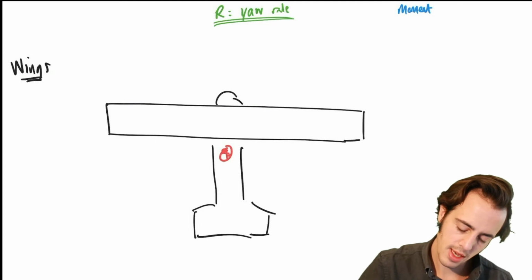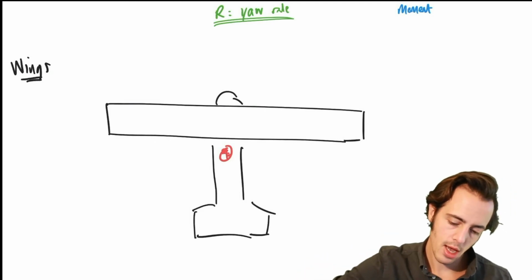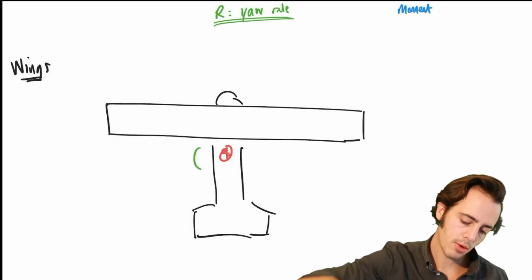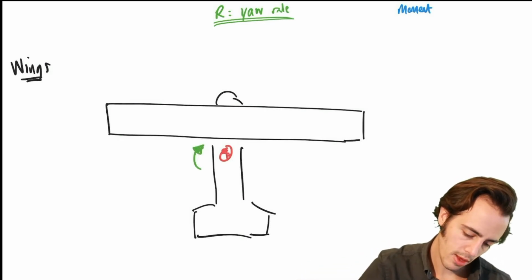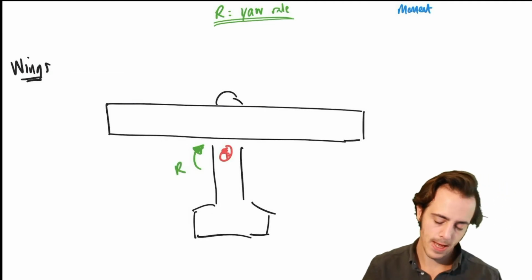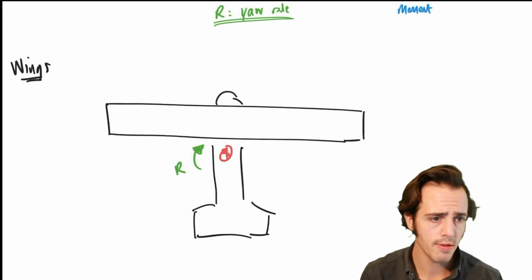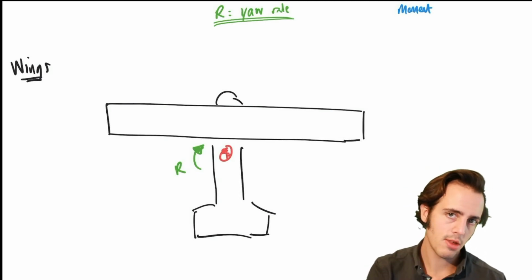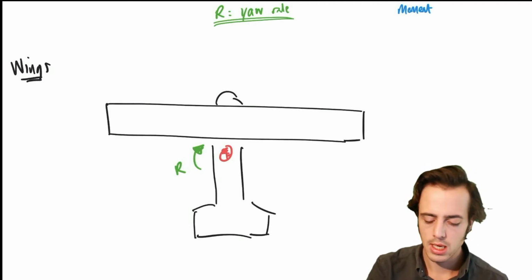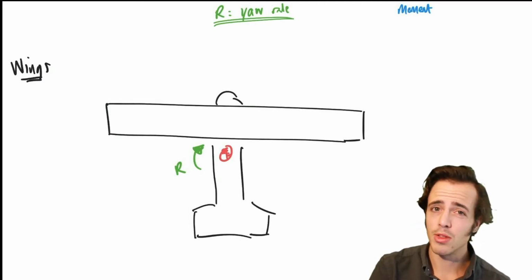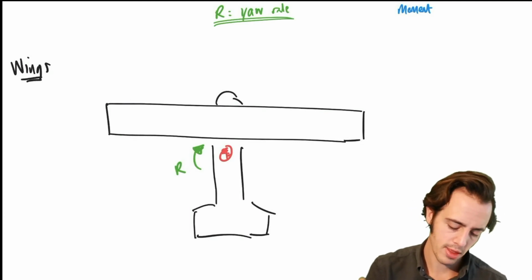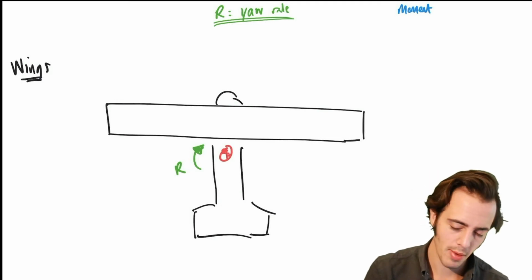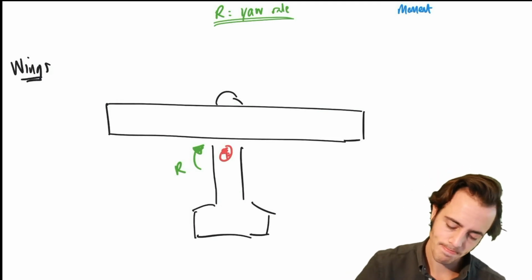Got our aircraft centre of gravity, and we're going to have a positive yawing motion. So we've got this yaw rate. Remember, thumb down. So we've got this here. It gives us our yaw rate R. Because we're just looking at the signs of these, we can work in terms of these derivatives with respect to the dimensional rates, because I don't want to bother looking at the non-dimensional, because we're not doing much algebra here. We don't need to bother with the non-dimensional roll, pitch and yaw rates, because the signs of the derivatives are always going to be the same anyway, and it's the signs that determine the stability.